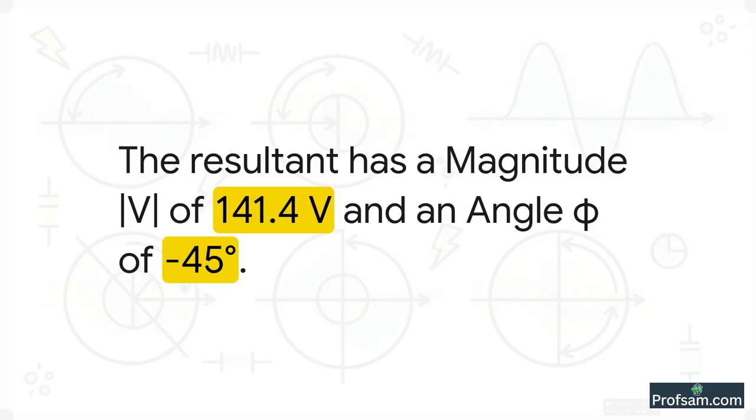And to find the properties of this new resultant phasor, we use simple maths. The magnitude, or the length, is just the hypotenuse of this right-angled triangle. So, using Pythagoras' theorem, it's the square root of 100 squared plus 100 squared, which comes out to be about 141.4 volts. And the angle phi, you can clearly see it's minus 45 degrees.